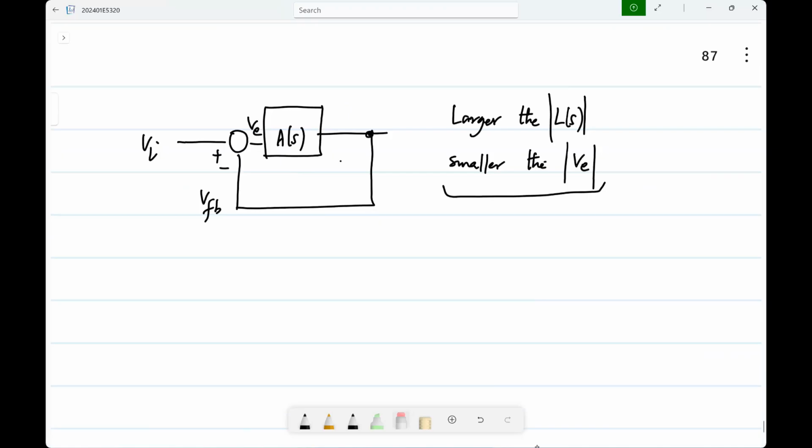If you reduce the signal by a factor of 2, the second order nonlinearity reduces by a factor of 4, and the third one reduces by a factor of 8, and so on. So higher loop gain also reduces the nonlinear products. Depending on where the nonlinearity is produced, but basically higher loop gain helps in many ways.